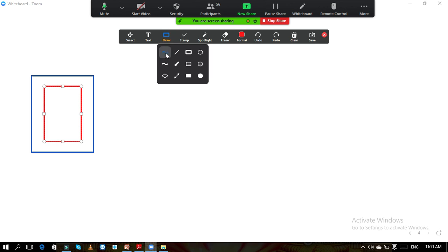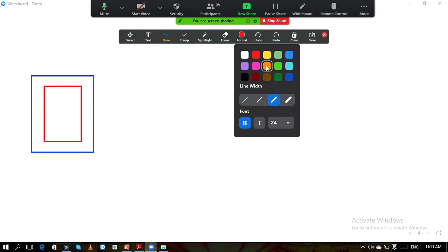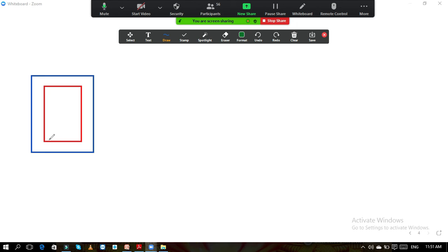Okay, and at the bottom now we have provided three bars of 20 mm diameter, right? So I will show those bars. So at the bottom our three bars are there. This is first bar. Here it is our second bar. Here it is third one. These are the three bars of 20 mm diameter. And top we have provided two bars of 12 mm diameter.